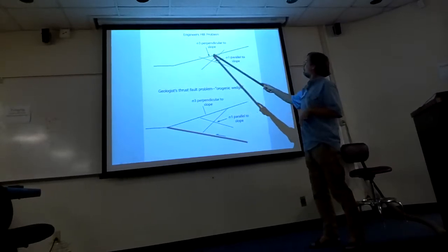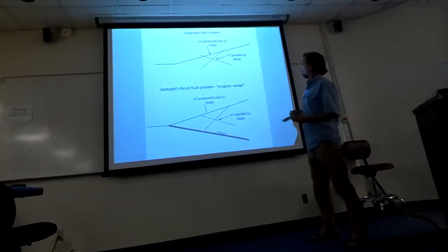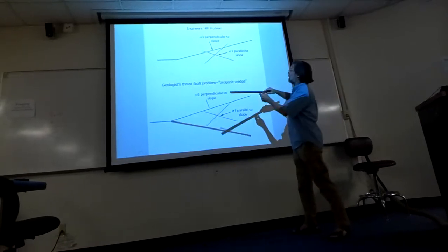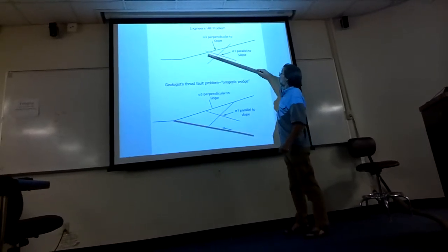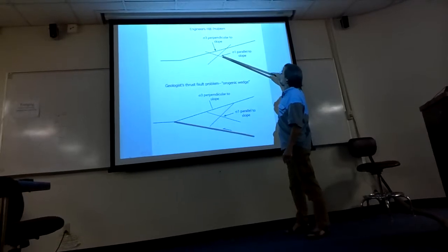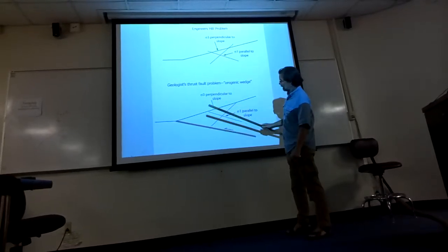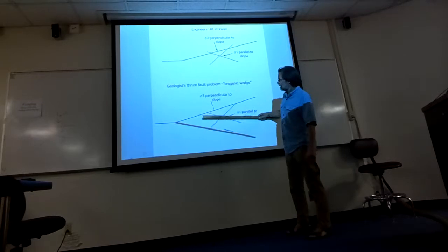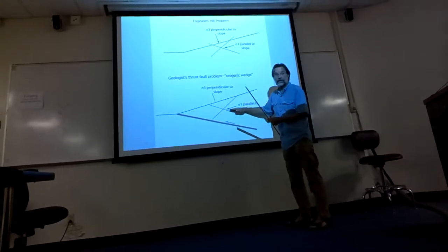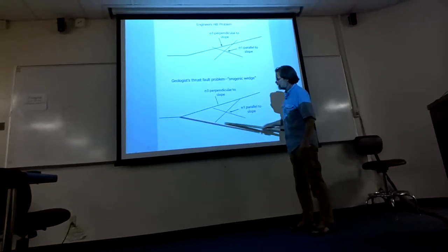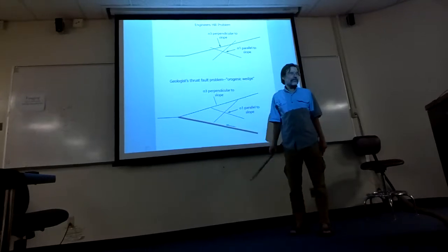When you're on a surface slope, the minimum stress may be sitting in here, the maximum stress is down the hillside. And what that effectively means is that, if this is say a slope of 30 degrees, then your two principal stresses are drawn 30 degrees from there and 30 degrees from there. This one suddenly has a very much lower dip than it would if this was tilted back this way without the presence of the surface slope. It would be down in here. And what that means is if you have a surface like this that's underneath this, you can make this slide because of the surface slope. This slides under a different stress state condition.